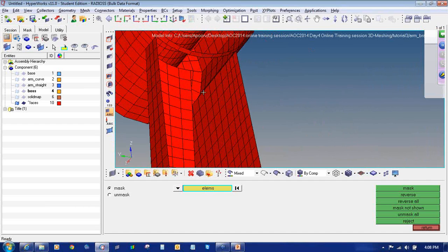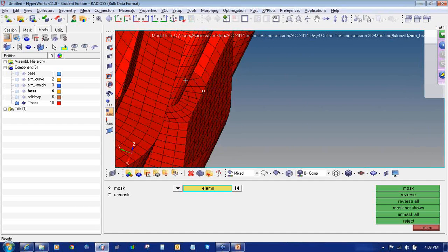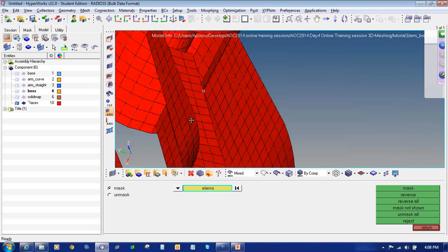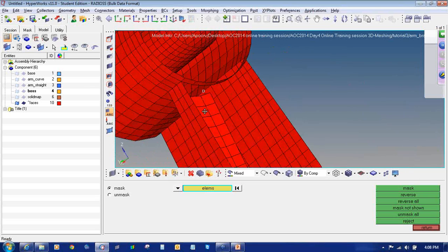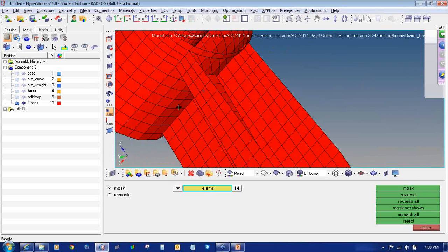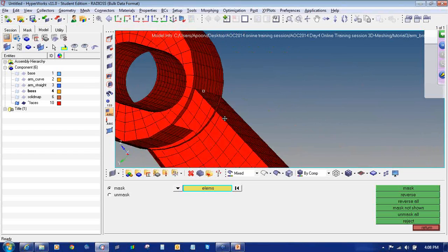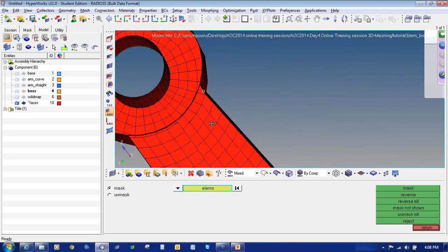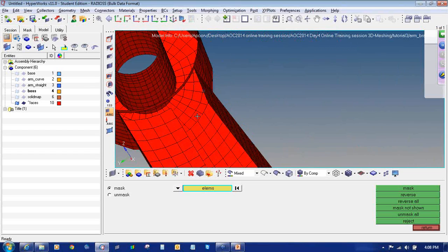So this portion has to be hollow or it's through. So it is now corrected. This is showing the edges because it has no elements here. So now this one is perfectly connected. Now my elements are perfectly connected throughout. So in this way you can check the element connectivity and improve that element connectivity also.